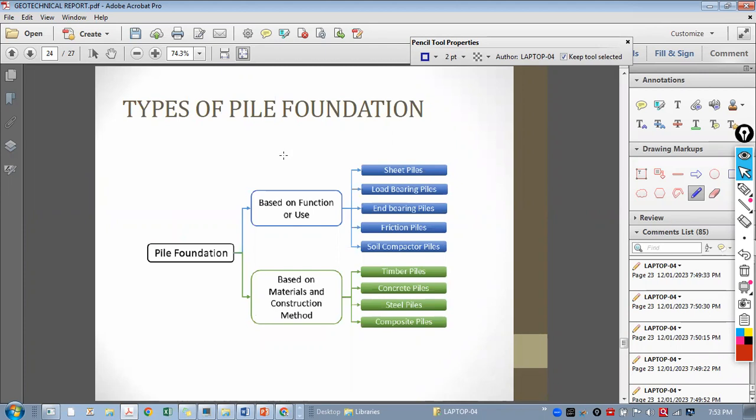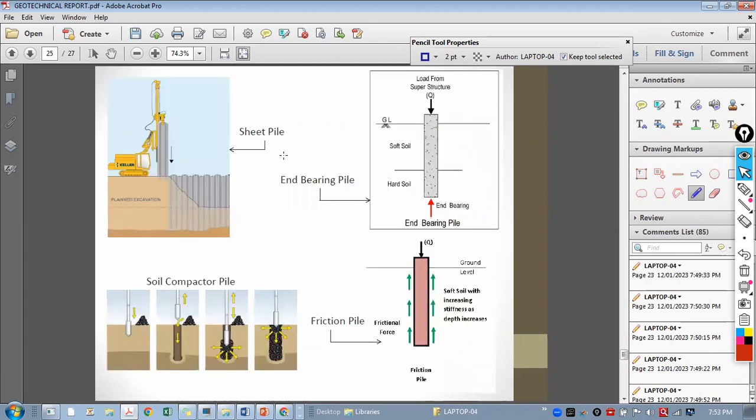See, the types of pile foundation will be decided by the geotechnical consultants. For just understanding, this is how we decide the capacity of piles in soil. There are two parameters by which the capacity of the pile is decided. One is the skin friction. As there is soil over here, this soil will have a frictional resistance around the pile, right? That we call skin friction.